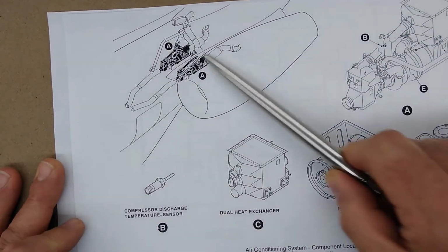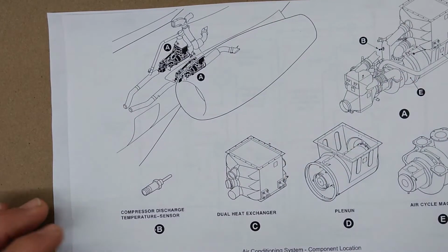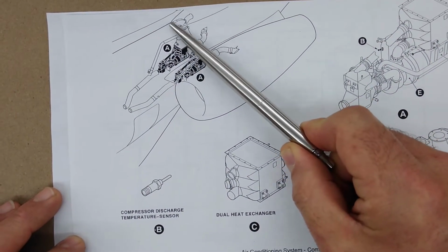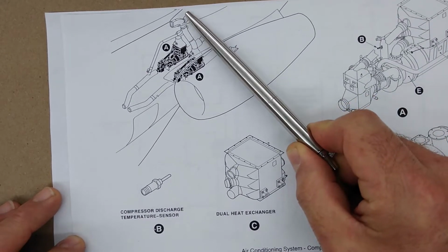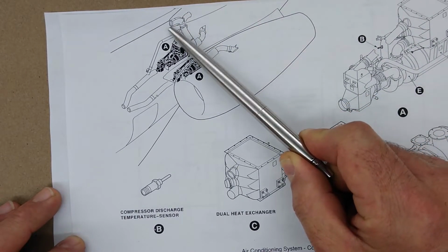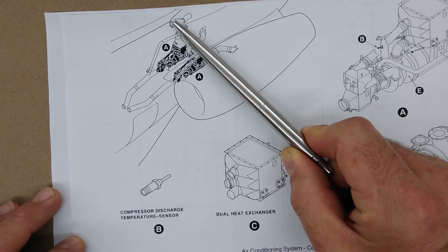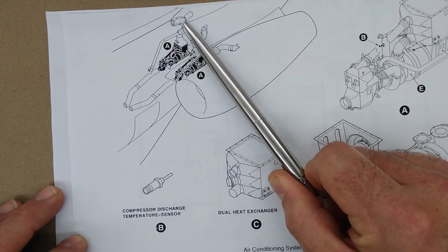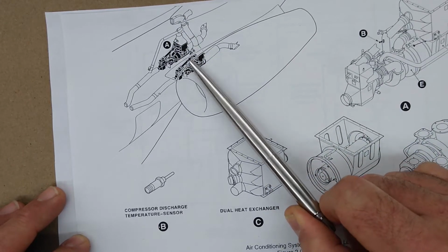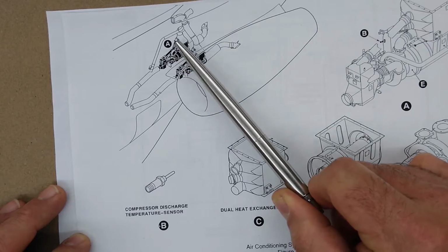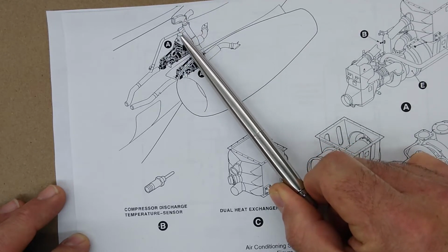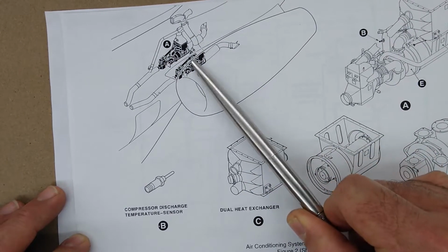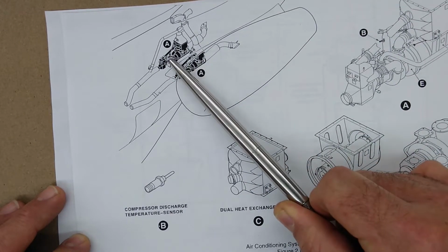Here's the left engine, right engine would be over here, and inside of here, this cone right in front of the rudder is literally an opening, an air scoop, to get ram air picked up through there and routed into the left pack and the right pack, and it splits through this white duct here, supplying ram air into the packs.